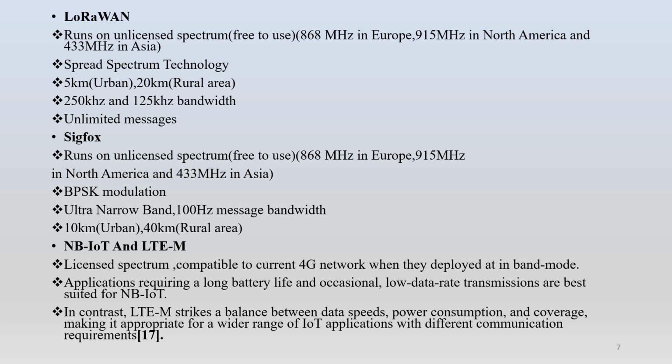It uses the chirp modulation technique, that is chirp signal spectrum. It is a type of spread spectrum modulation that employs chirp signals for transmitting and receiving data. So, what's a chirp signal? It's a signal in which frequency continuously increases or decreases with time.